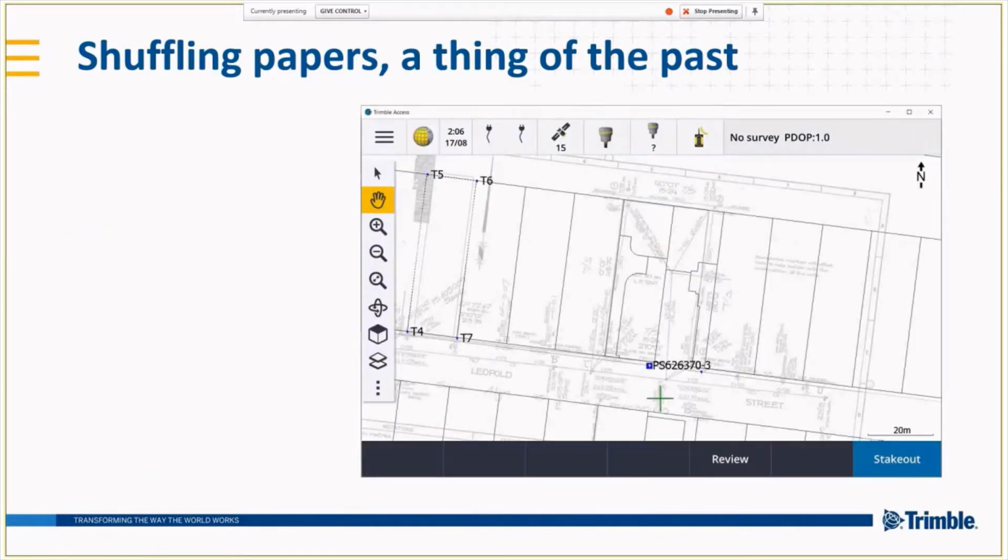Yep, here we go. We're connected to a GNSS, and we can actually walk over the map, which means that we could roughly see what the descriptions were for these survey marks as we walk along out in the field, for these being might be a rivet or a chisel cut or some other survey mark being placed. So it becomes, I find, quite convenient compared to taking out a sheaf of papers and a folio still. And it has that added benefit that you're actually seeing it in reference to what you're doing on the ground as well. Depending how you want to georeference it, then it makes it quite a bit easier.